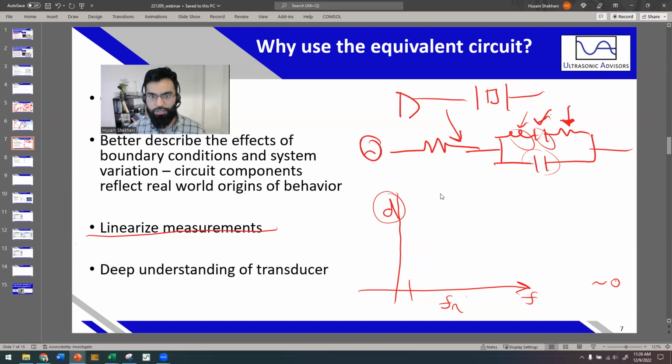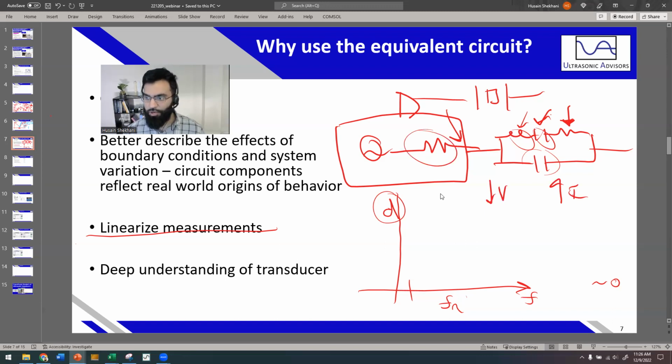There's the voltage source here, and it effectively keeps the current constant at the resonant frequency. Not the voltage, sorry, the current constant, because the more current this system draws in, the voltage will automatically drop due to this resistor. That really does happen for most drivers.